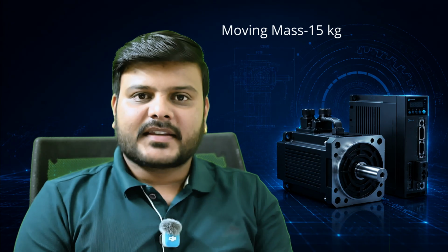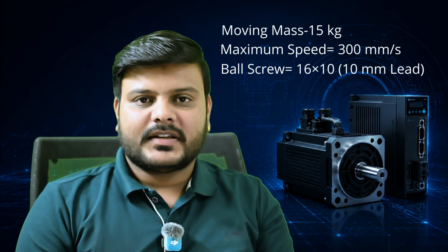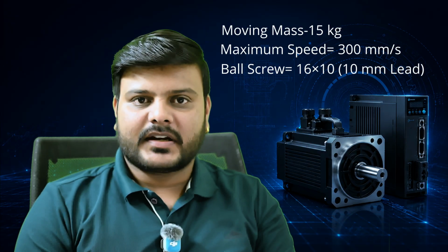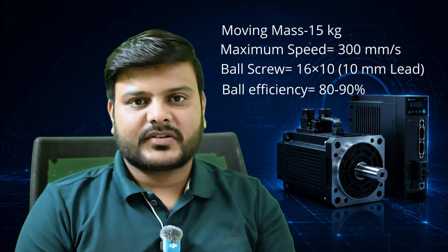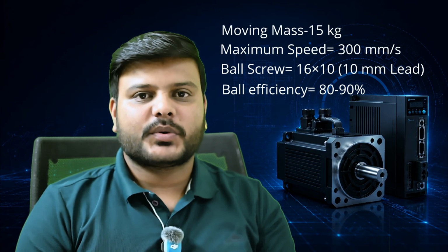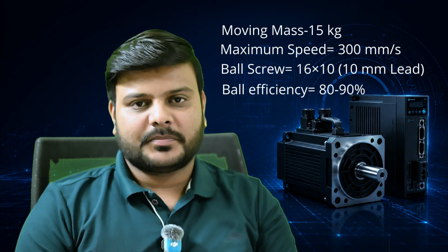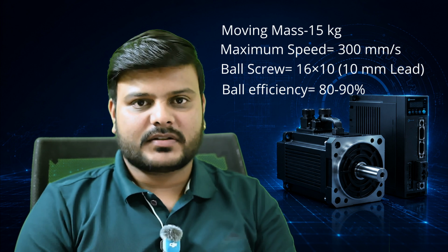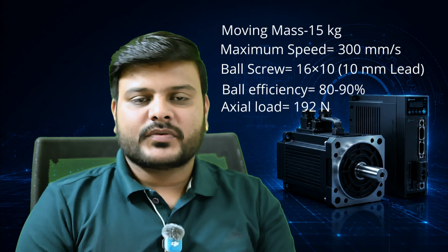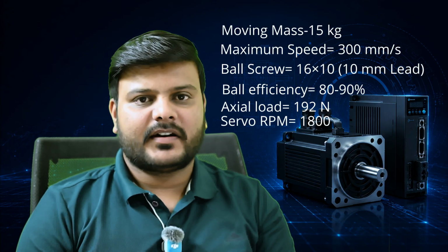Our moving mass is 15 kg, maximum speed is 300 mm per second, and the ball screw lead is 10 mm, which we selected in the previous video. As per the manufacturer's catalog, we must select a ball screw efficiency of 80 to 90%. We are considering 90% efficiency for our calculations. Our maximum axial load is 192 Newton and servo motor speed is 1800 rpm.